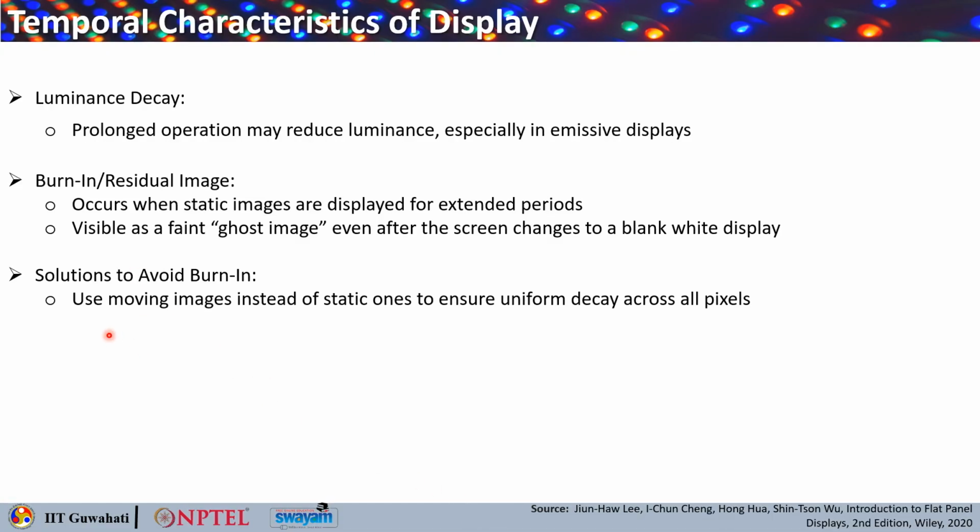So what is the solution to avoid burn-in? You need to use moving images, or you look for some static images which change over time, or some sort of static images that ensure uniform decay across all the pixels.